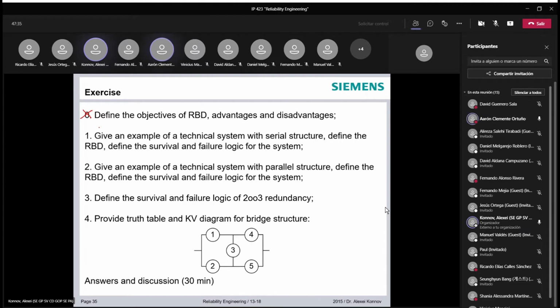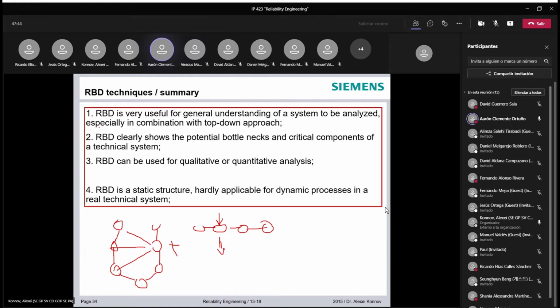When we negate an OR function, does it convert to an AND, or does it stay the same? Probably you wouldn't believe it, but yes, because I hope you remember the appropriate De Morgan transformation rules. This is the first one: if I have A or B all negated, that would be converted into A negated and B negated.